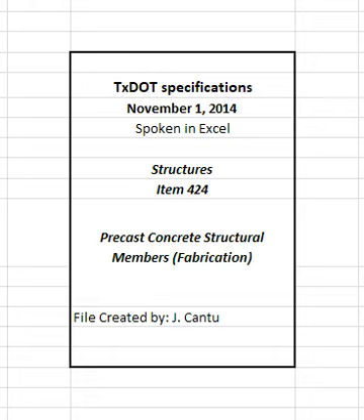Place concrete as near as possible to its final position in the forms except when using SCC. Do not deposit large quantities of concrete at one location and run or work it along the forms to other locations except for SCC. Place SCC in a manner to avoid segregation. Do not allow fresh concrete to free fall more than 8 feet unless approved. Work the coarse aggregate back from the face of the concrete, and force the concrete under and around the reinforcing steel, strands, embedments, and ducts.